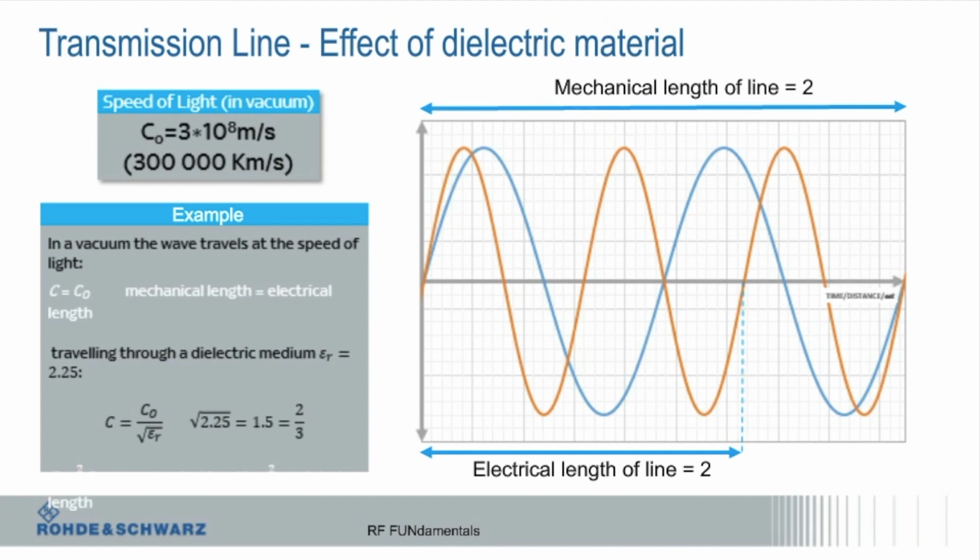But my point is more, you'll often see where somebody, maybe they have an SMA cable from their whatever, and then they connect it to a BNC, and then the BNC connects to another BNC, which connects to an N, which goes to the instrument. Every interface there is degrading the standing wave ratio. So you're getting reflections from each of those connections. So A, use really good connectors, if you care about this, and B, minimize the number of connections. If you have an SMA and you need to get to an N, get the right adapter. Ideally, get a cable that has the right connector for that interface. That's really more the moral of the story.